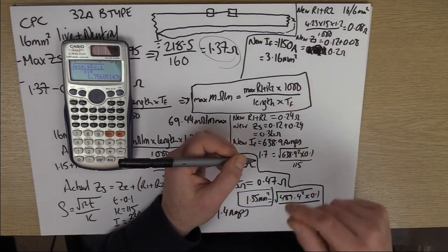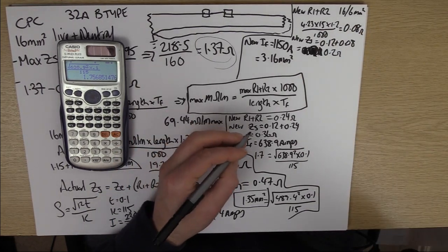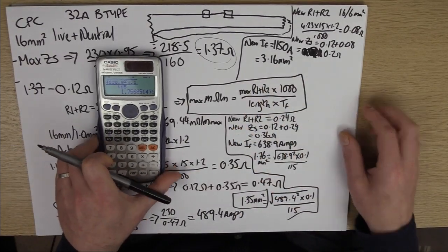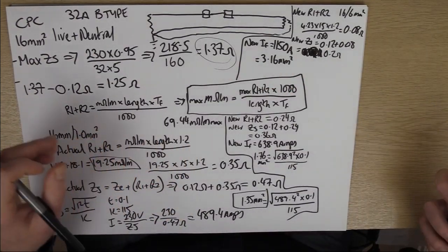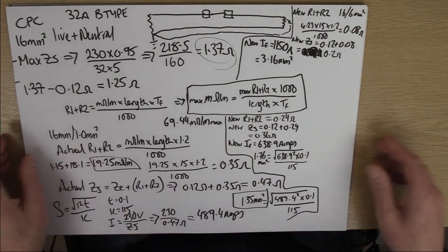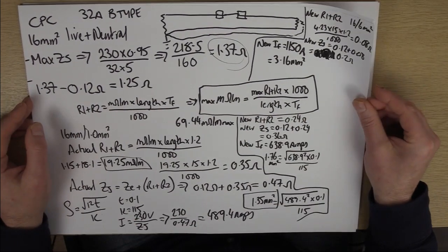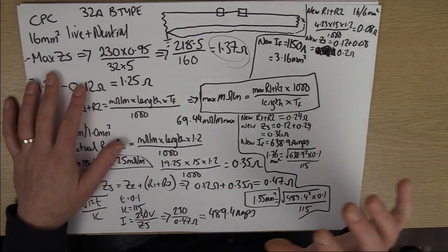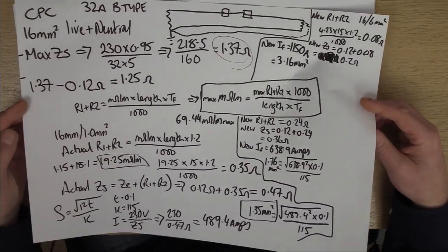And that's when we jumped to a more sensible combo that makes sense in your head, doesn't it, logically? And now it works. Now you probably could go down to a 4mm, but to be honest, I think I'll be tired by that point. I'll just go, oh, 6 will do. And at the end of the day, as long as this all complies, then the circuit should work. That's what we're after. So it's always two checks for CPC. It's your ZS, but it's also its adiabatic. I'm quite pleased with that example actually.